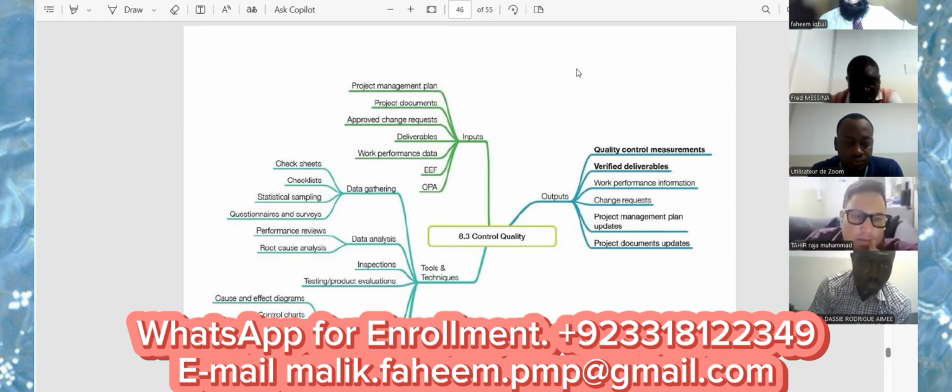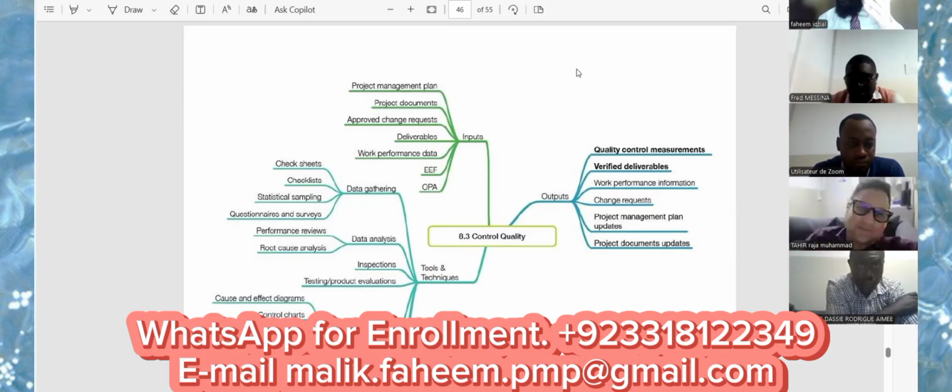If you are doing welding of, for example, a penstock joint, you have 7 units, and the length of the units is very big, I think 2 or 3 kilometers like that, and you cannot perform the inspection of every joint, then you will use statistical sampling at that joint. Or you are doing work inside the refineries, and there are so many pipes. We are using CS there, alloy there, and so many other materials. There are so many joints of the pipelines, and there you will use statistical sampling.